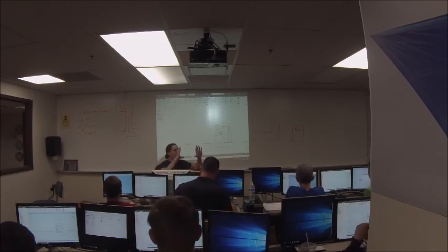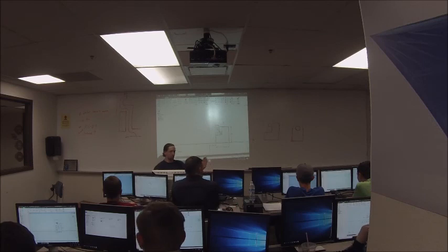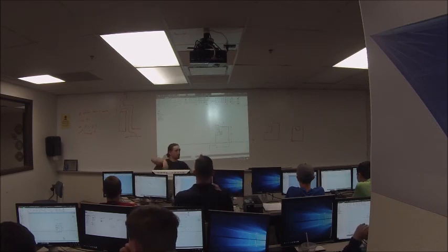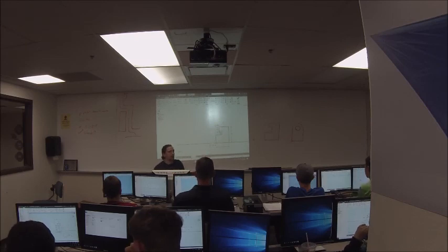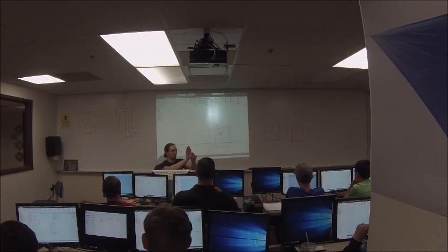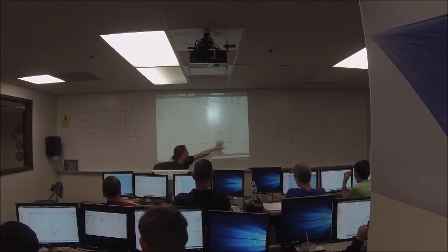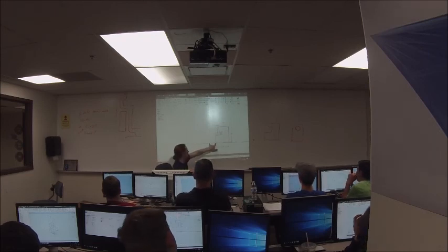Okay. So if I had a box, I could use the left side of the box, revolve it, and I would get a cylinder. But in this case, we have a little more complicated part. I want there to be a hole through the center of the part. All right, so I don't want to revolve it around its one side. I want to revolve it offset in the sketch. That's why I was so adamant about you guys having this gap between the origin and your part.